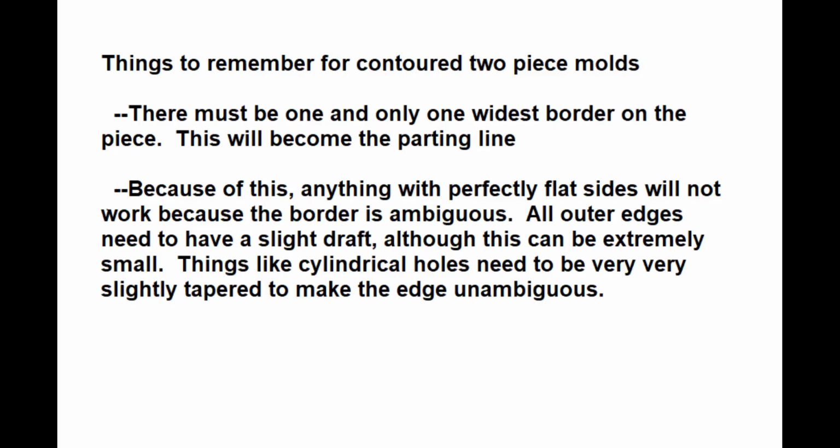So here's another case where we need a non-planar contoured mold. Now one very, very important point when you request a contoured mold is that it has to be completely unambiguous where the widest part of the mold is, and that will be where the parting line is placed. So for example, if you have a vertical cylinder, that actually won't work because the top edge of the cylinder could be the parting line or the middle or the bottom because they're all the same width.